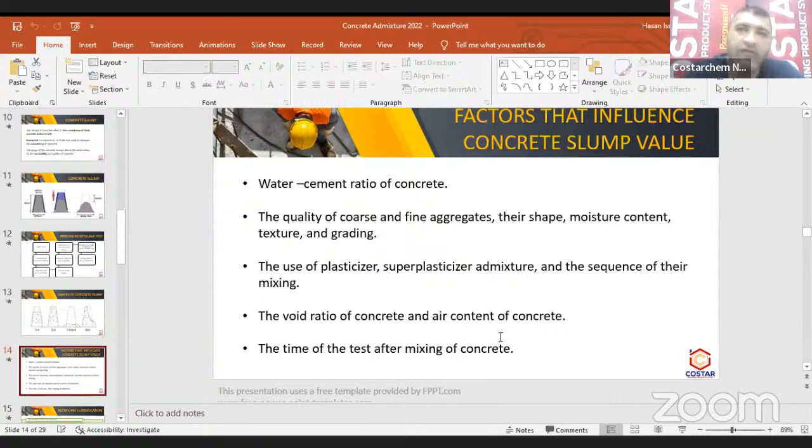Air is very important to the concrete. So why is air important to the concrete? Now, the entrapped air, we hate it because it forms big bubbles, something like 2 mm, 3 mm in diameter, which promotes a lot of gaps inside my concrete. It will make my concrete more permeable to water, and more permeable means the probability of my steel getting corroded is higher than with fewer voids in my concrete, isn't it?